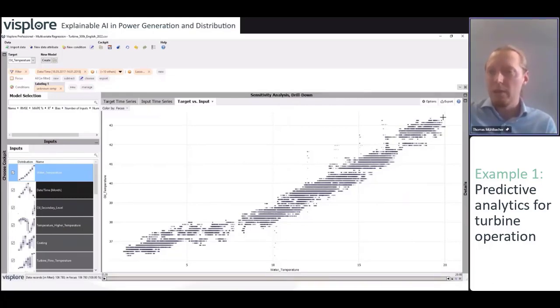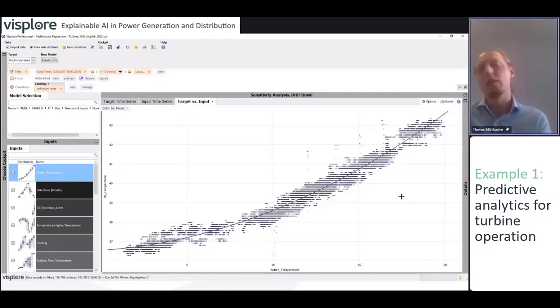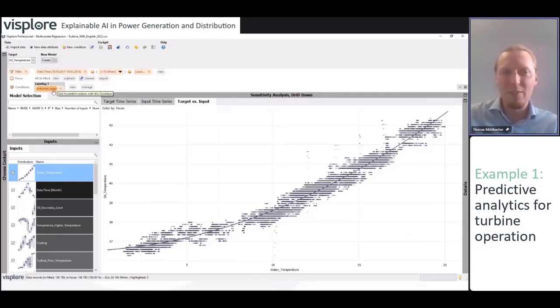And right here we can actually switch on a visualization of a regression line, maybe not only linear but quadratic. And then we can see that this relationship, oil temperature from water temperature, is actually something we can model quite nicely once we have selected the data. And even the dynamic tolerance corridor becomes quite evident here, because you see that roughly around 1 degree Celsius around this regression line is normal. And then you have these unknown ramps here that you see, which would actually be detected by such a rule. If you say more than 1 degree apart from this prediction should be detected.